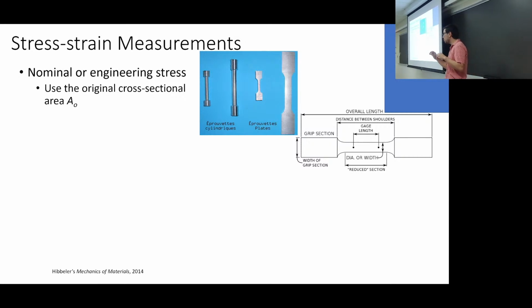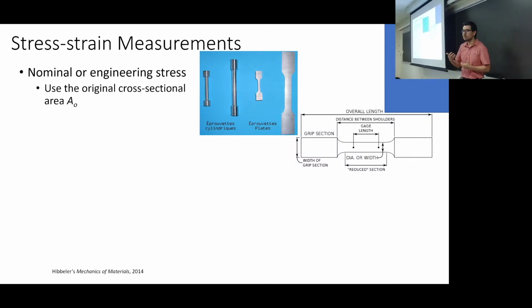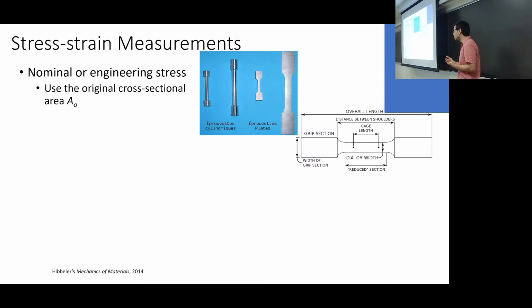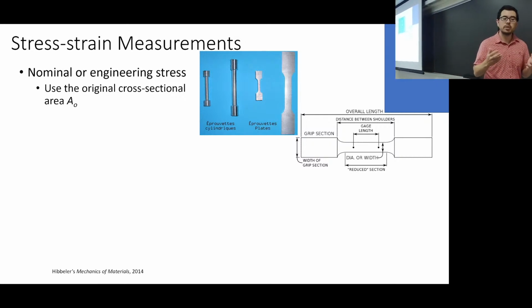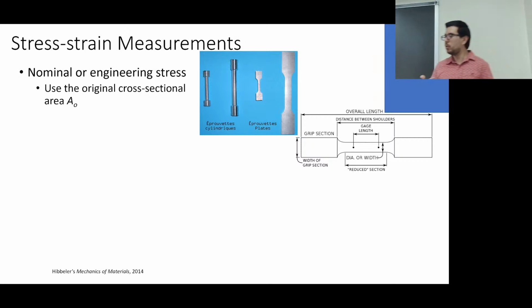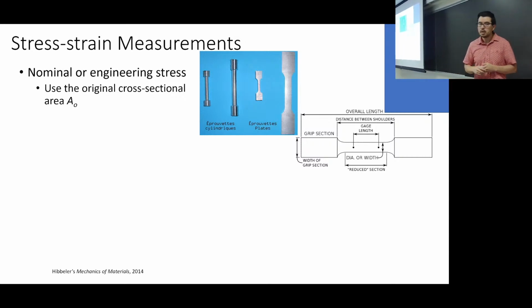And for materials like solids, rubber is an interesting material in that, unlike in your fluid mechanics, where we always say, oh, in water, volume is always conserved, it's an incompressible material, unlike a lot of the materials that we use in solids, rubbery materials are actually very close to conserving their volume. The metals that we use actually don't conserve their volume as well. But it's not a key component to think about, because we think about the metals more than we think about rubbery materials in this class.